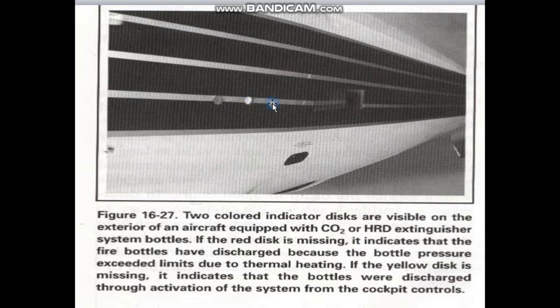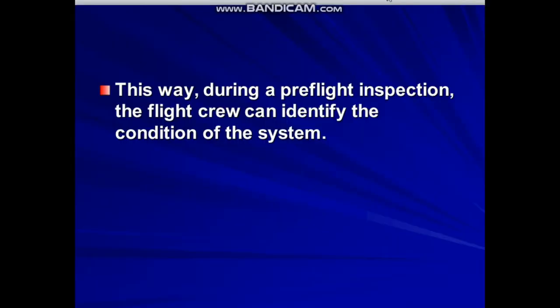What about the yellow indicator? If the yellow disc is missing, it indicates that the bottle has discharged through activation of the system from the cockpit controls. This way, during a pre-flight inspection, the flight crew can identify the condition of the system.